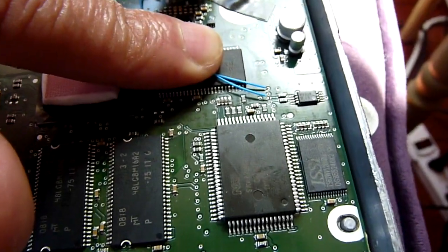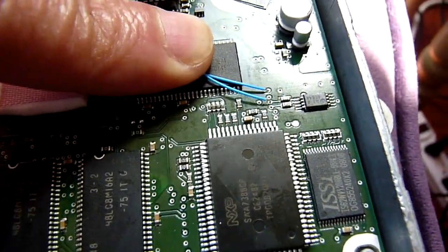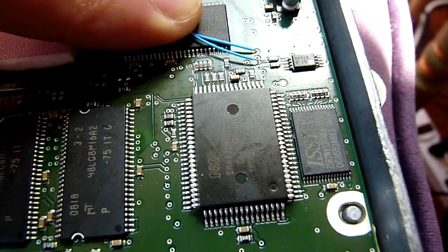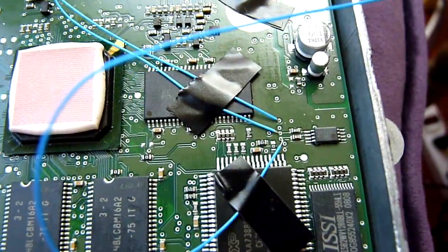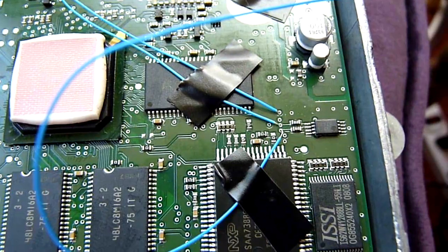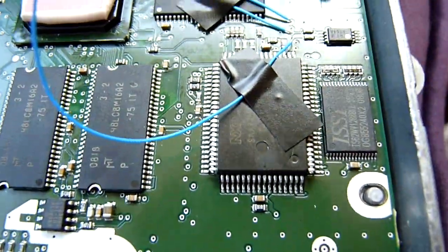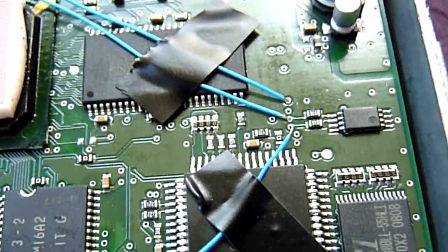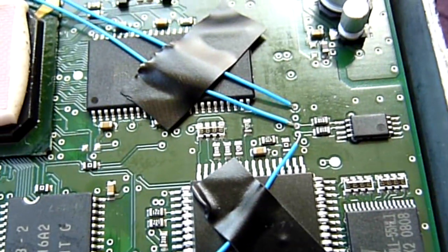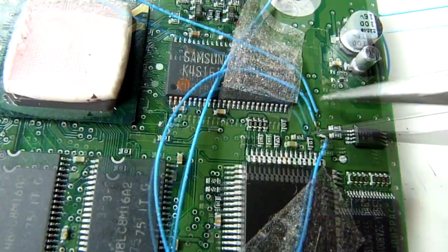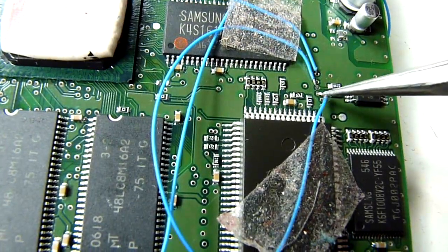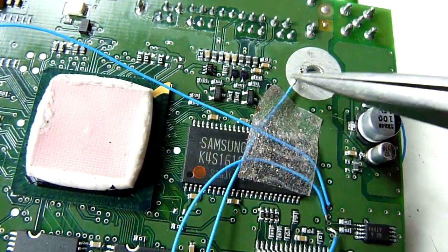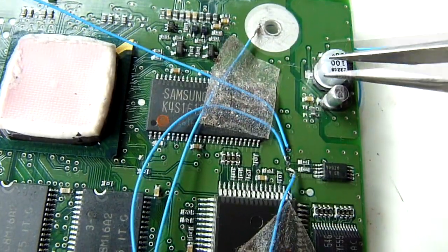So now I have VCC. Make sure between those two there's a via. Okay, that via is not. So now I have all the ground, the VCC, pin 5, pin 6, they're all taped down, and they should make contact. So now we can do the reading and programming. This via, the first one here is VCC, and this is pin 5, and this is pin 6. And this one is ground on the way over here, which is pin 4.